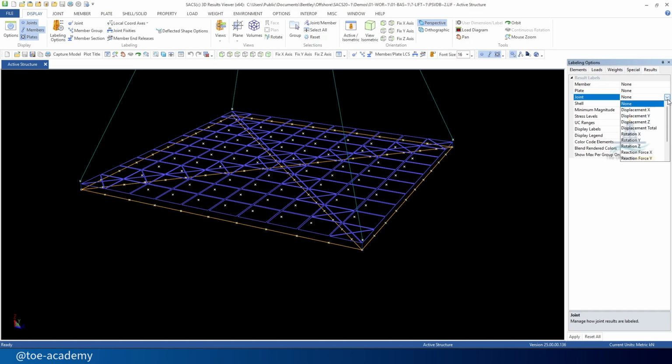The next most important one is the joint reactions. That should be very minimal. So for that you can check here joint reaction X is 0 and joint reaction Y is 0. So our lift analysis, the analysis procedure is good, and this is how you do a lifting analysis with DNV factors. And next class we will be looking at how to do a skew analysis.